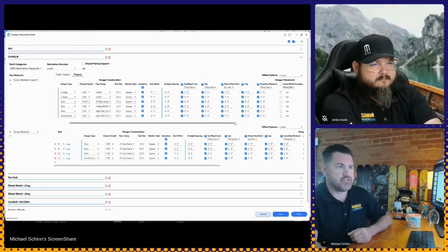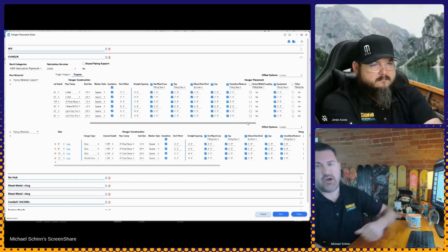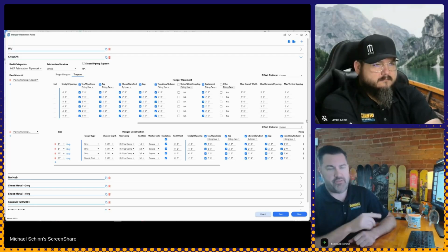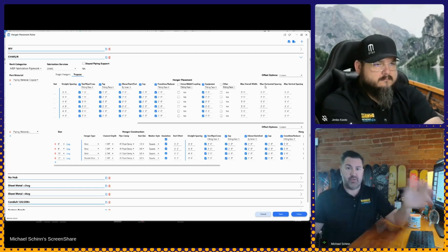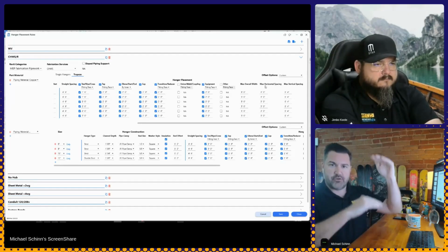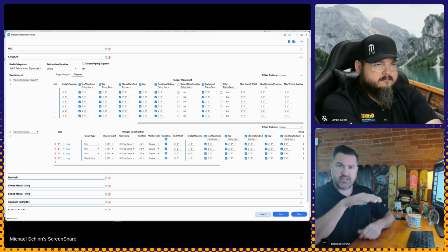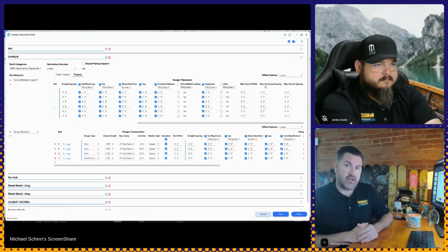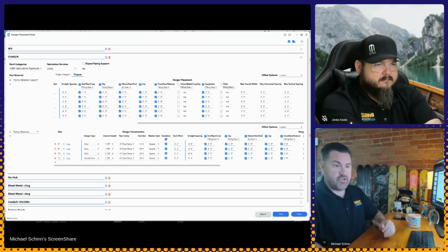And again, all of your same rules. What is the spacing of those hangers? We also have further downstream here with your trapeze, what's the max overall width that you want a trapeze to be? What is the max horizontal spacing between pipes before it makes a new trapeze? And what is the max vertical spacing before it makes a new tier? So with these rules, it's basically set it and forget it type of concept here. Just be able to set your rules, and that's it.